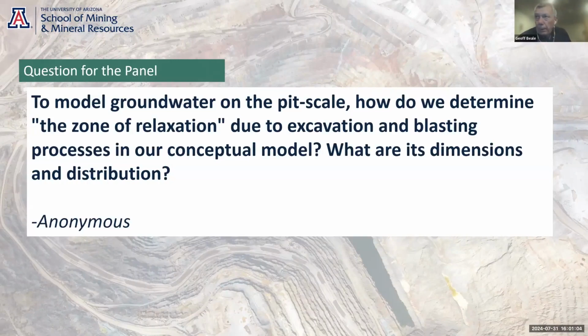Lots of people have done permeability testing in horizontal holes and sampling in horizontal holes to try and look at the effects of dilation. But probably the most robust system is to look at the piezometers and to see how the piezometers respond to mining the slope.